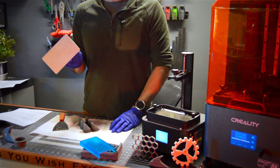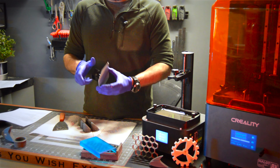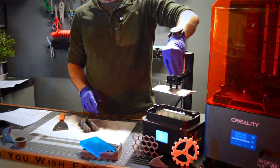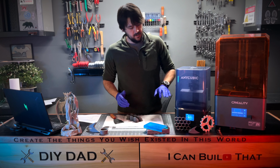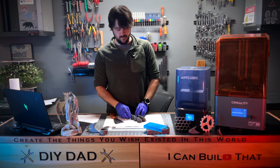If your build plate is clean at this point, my experience has been that it's perfectly acceptable to place this right back on your printer and continue printing without needing to clean the build plate itself. Once it's completed, go ahead and replace your cover so that UV light isn't hitting your resin vat and interfering with the resin that remains in the printer.